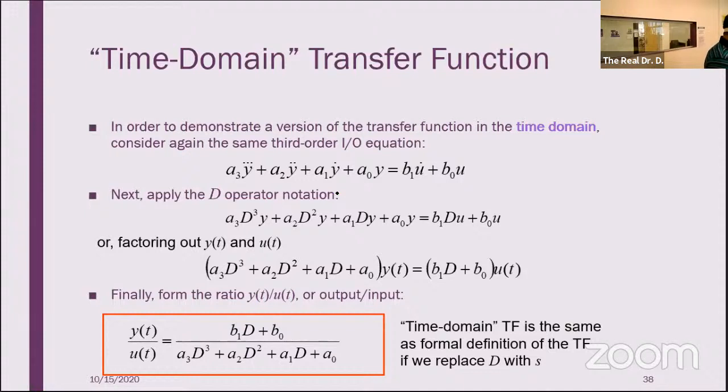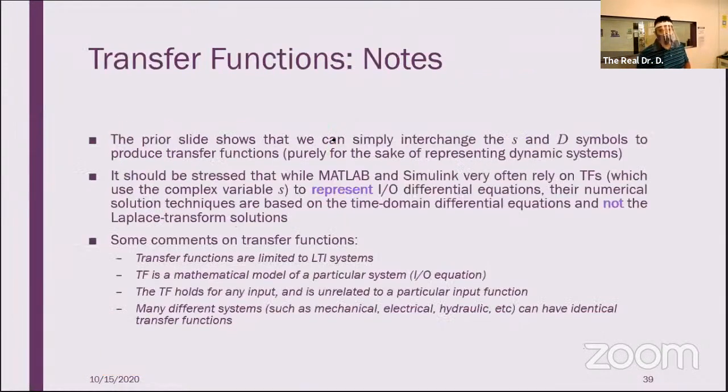So if you're asked to find a transfer function and you're given initial conditions, you are supposed to summarily ignore them and treat them as if they are zero. A transfer function is a very specific thing. The initial conditions of your system are zero when you're looking for a transfer function. We'll talk about why when we get to Laplace transforms.